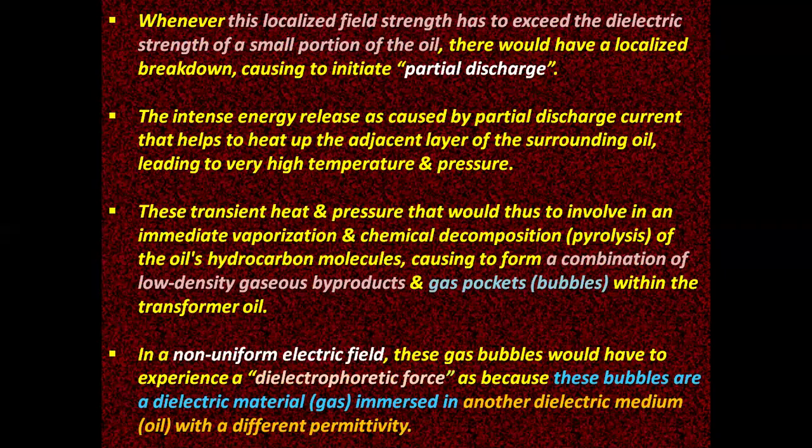Whenever this localized field strength exceeds the dielectric strength of a small portion of the oil, there is a localized breakdown, initiating partial discharge. The intense energy release caused by the partial discharge current heats up the adjacent layer of the surrounding oil, leading to very high temperature and pressure.